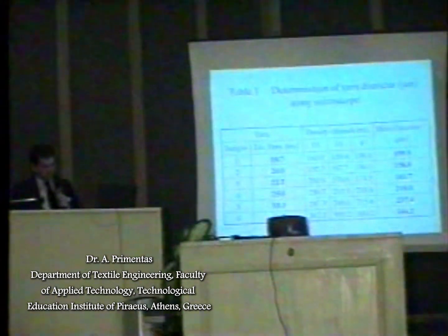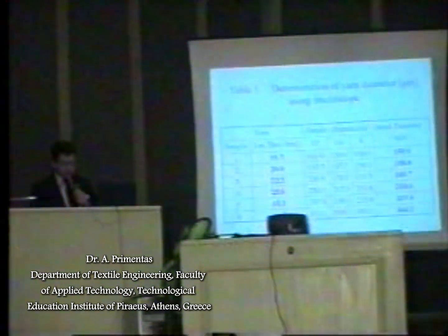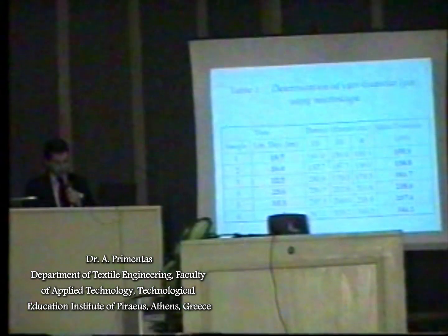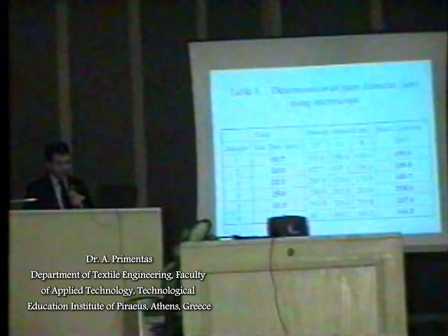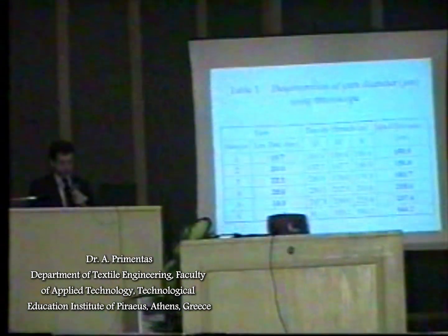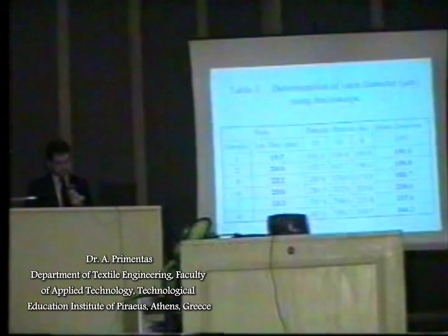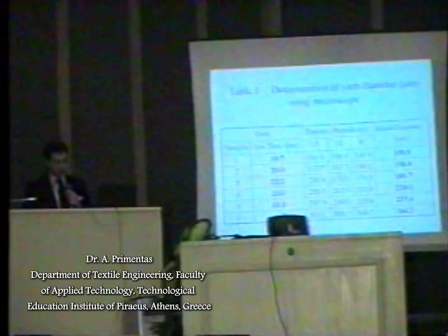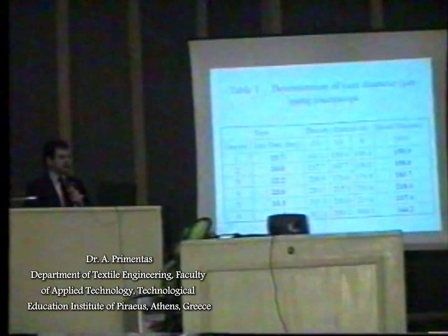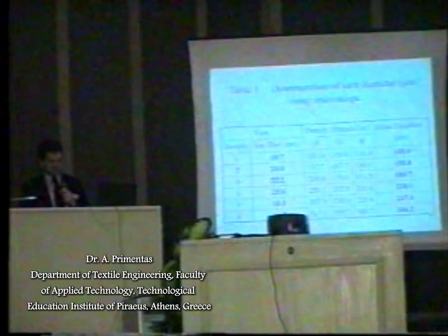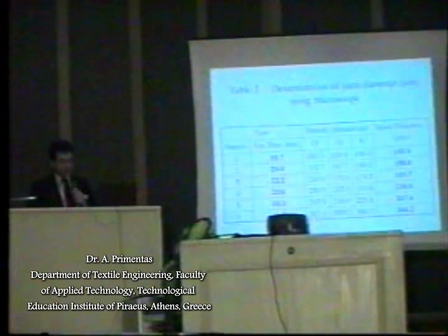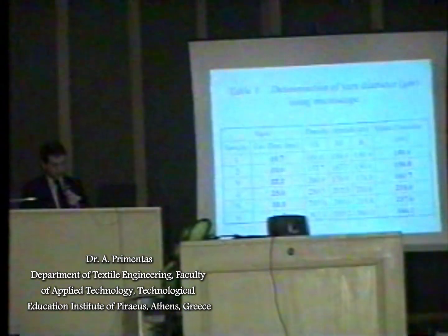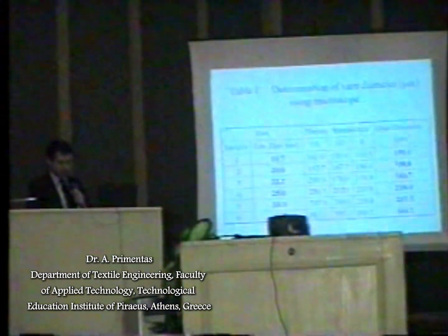In the experimental work, the effect of the wrapped yarn density on the determination of yarn thickness/diameter was under investigation, as the area of the pressure foot on the fabric thickness device was fixed. Thus, after experiments, it was decided to use 3 densities of 8, 10, and 15 threads per centimeter. 18 frames were prepared with carried cotton yarn samples of 6 various linear densities.